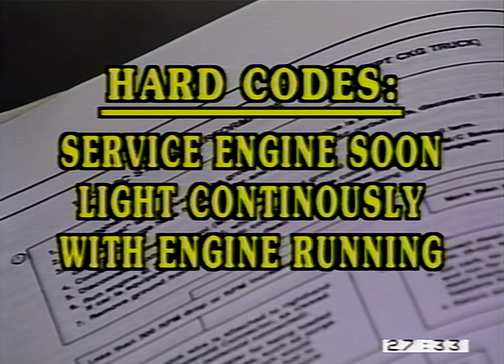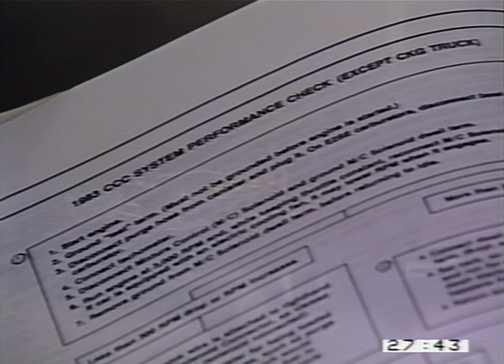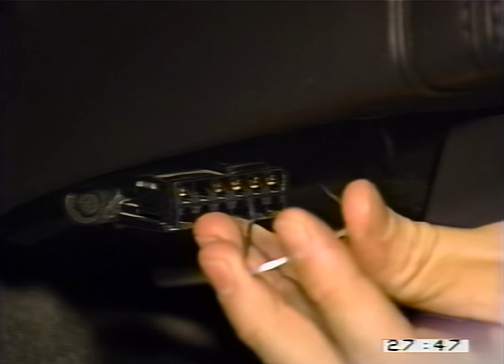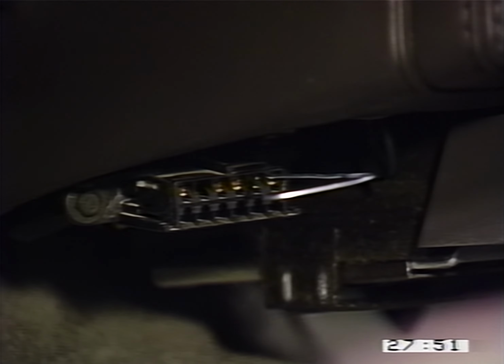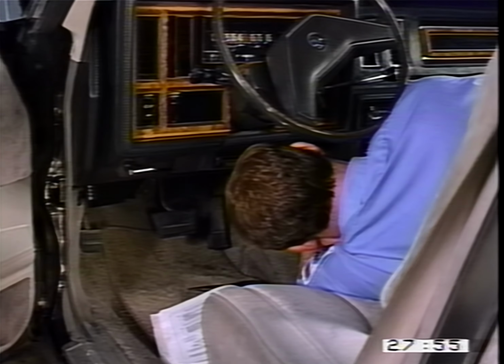Hard codes trip the service engine soon light to burn continuously when the engine is running. Diagnostic charts will usually not help to analyze intermittent codes. Here's how to distinguish between hard and intermittent codes. Enter the diagnostic mode manually. Read and record all the stored trouble codes you find. Exit the diagnostic mode and clear the trouble codes.